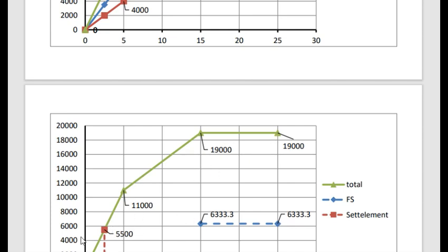So in this case, of course, a pile load test will not be straight lines. It will be a curve, a pure curve. But once the pile reaches the failure load, I will find that more or less I will have a line which is similar to this one. Why will I have a line? Because it's failure. It means that without adding additional loads, I'm having settlement. So this is the failure load of the combined friction and end bearing.